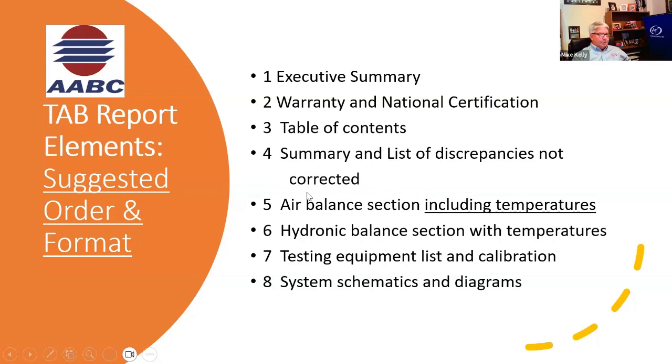Air balancing shouldn't just be air balance. As far as airflow numbers, you should have temperatures to follow and double check things. Hydronics is the same way. You should have temperatures to substantiate the water balance.